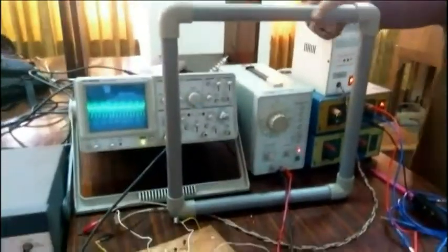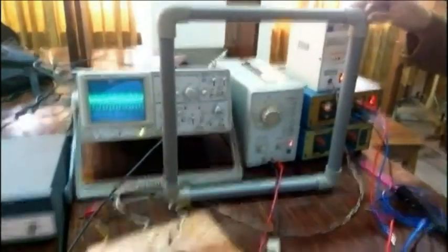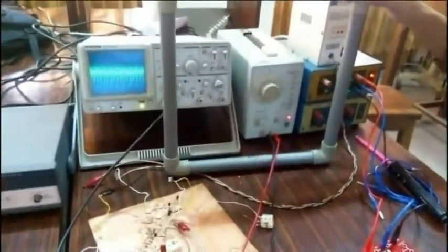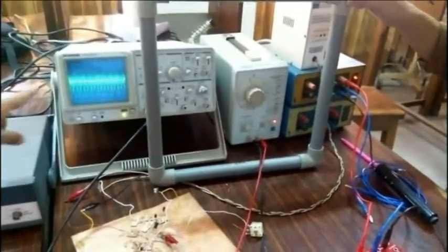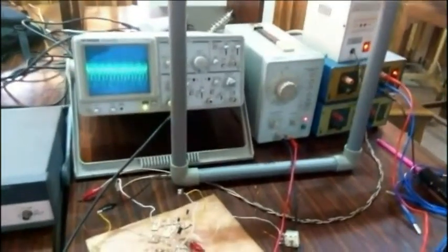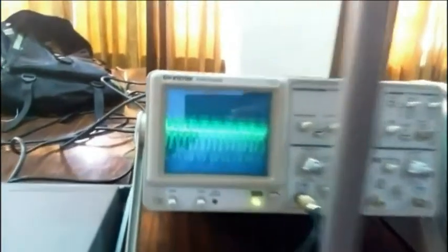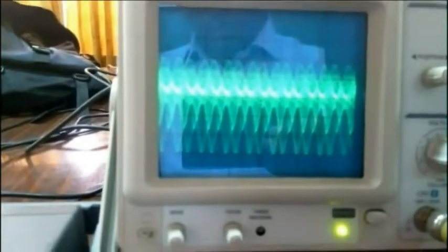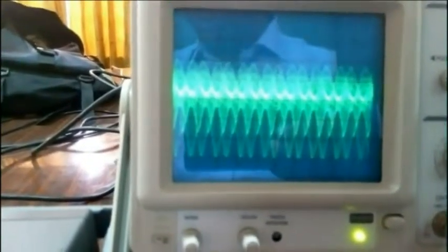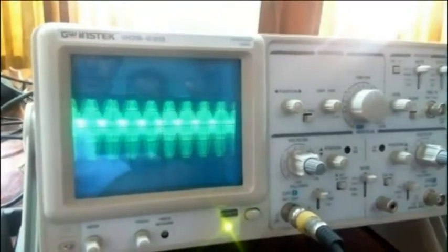This is our antenna, which is a loop antenna of 1 foot by 1 foot area, which accommodates 6 turns of coil. The amplitude modulated signal has almost 10 volts peak to peak, which is high enough to be received by the receiver circuit. Here our AM modulated signal is transmitted to our receiver circuit and is caught by its own antenna, and finally it is reached there.